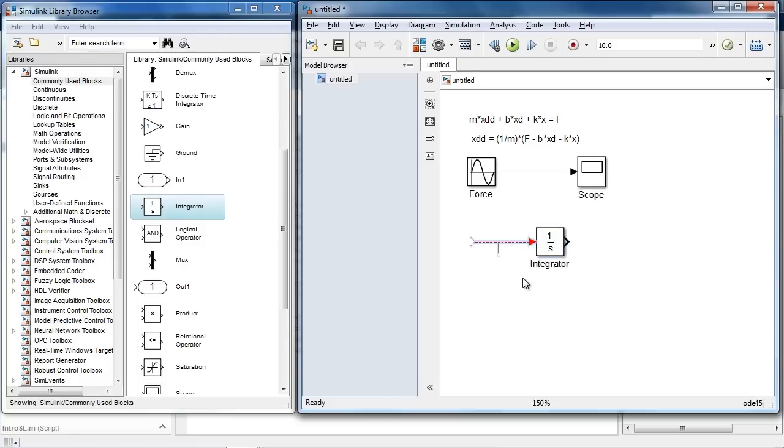All right, now what did you just drag in here? Oh, so this is an integrator block. So this block will integrate whatever's on the left-hand side, which in this case I'll define as x double dot, and this is why I reformatted this equation, and we'll see how this works as I build up the model. Okay. And when I integrate that, Michael, I'm sure you can guess what's going to come out on the right-hand side. X dot. Exactly. Yes.